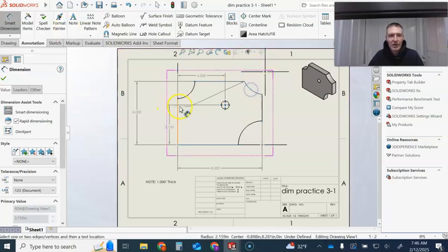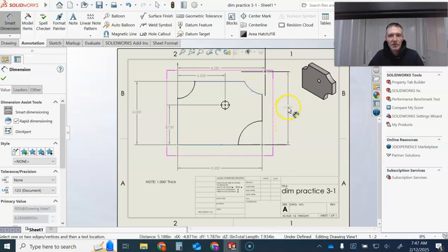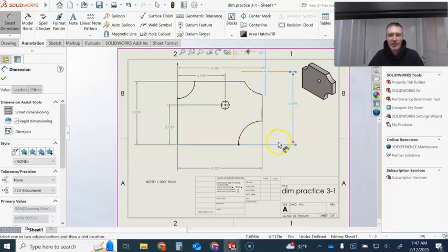I'm going to select this arc and I'm going to go over here to this side and I'm going to drop this in. Okay, stagger that up a little bit. And now I know where the arc center is that way, but from the bottom, where is that arc center? And I'm going to go from the bottom here over to this arc and I'm going to measure up. And I'm going to move it out because it's kind of like the tallest dimension here. So everything else will fall in between and won't cross dimension and extension lines. All right, so now I know, oh, okay, this is 898 above this surface and 281 beyond this surface. Okay, so I already know that. So there's my arc center.